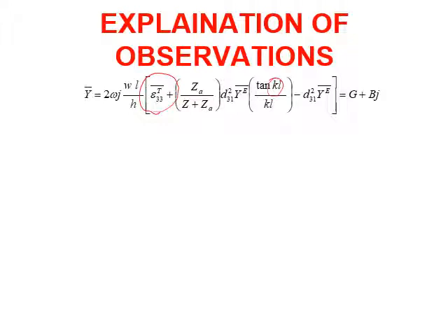So this is the equation. What we find here is that if we see these two parts, they are independent of the structure, epsilon 33 T bar and d31 square Y. They are sort of inert and they make up the capacitive component largely, and the structure part appears here in the form of the Z. So this part is very much dependent on the parameters of the structure.